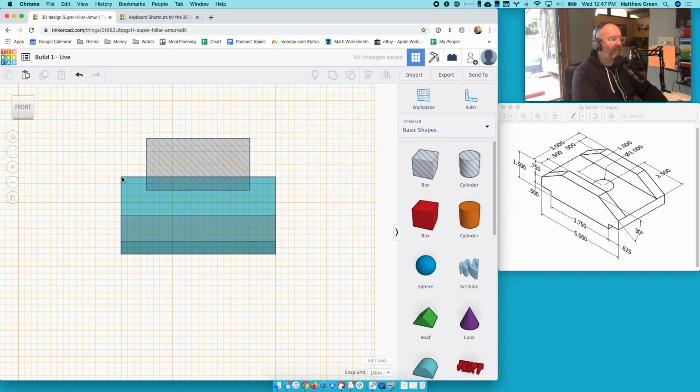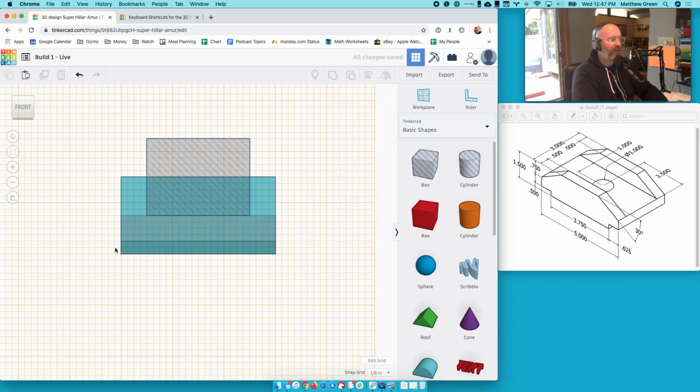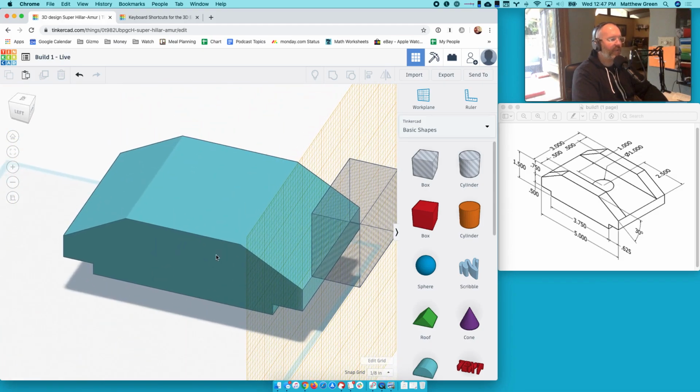And here's what I mean. The distance from here to here is 1/2 inch. Distance from here to here is 1/2 inch. That's good. And then I need to take this and go down, cutting into the object. There's 1/2 inch. And there's 0.75. And you can actually see it's right in line with that previous, which is good.